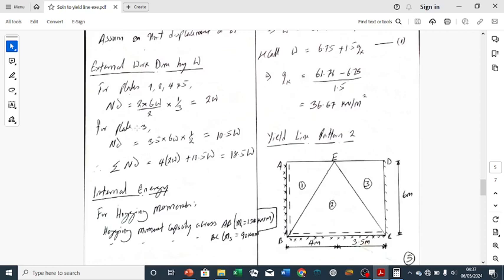So we can now say that the area, half base times height, is 2 over 2 times 6 over 2, multiplied by W, which is our UDL. And our displacement, like we said in tutorial question 1, because it is a triangle, we use our delta as 1 over 3. So that gives us 2W for each of those plates.